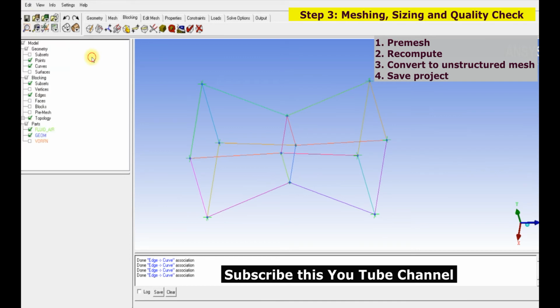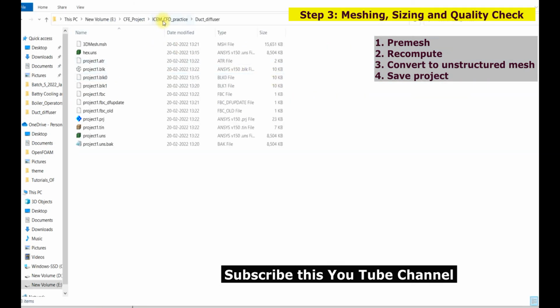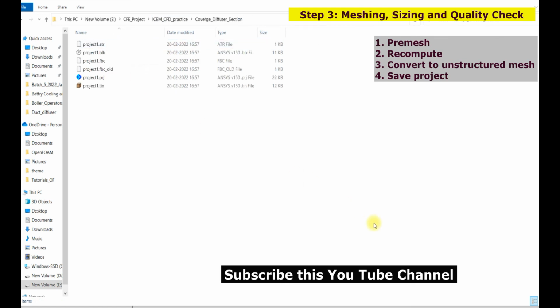You can save the project. Here the ANSYS project is saved. Project file, FBC file, ATR file. You can check whatever files are saved here. See, these files are saved. And this block file is saved. Project file and tin file. Tin file is the geometry file. Please note this is a geometry file.